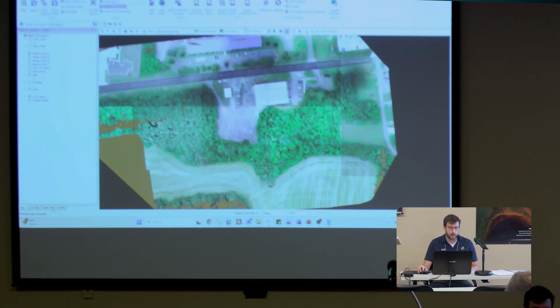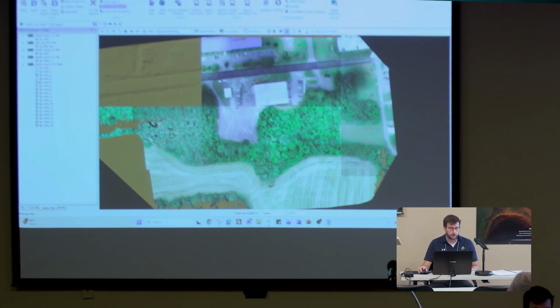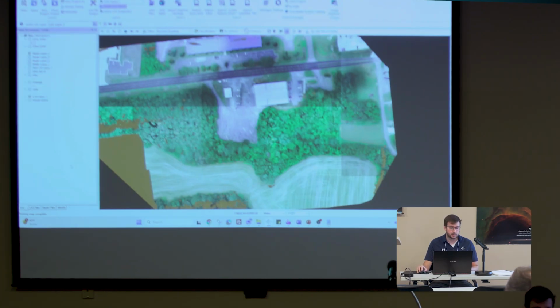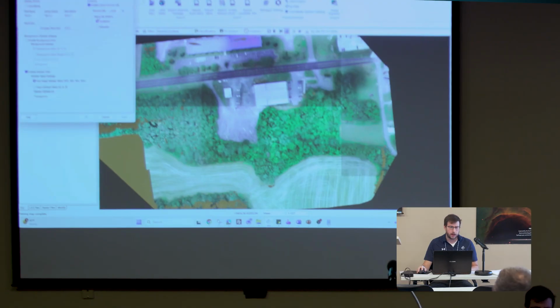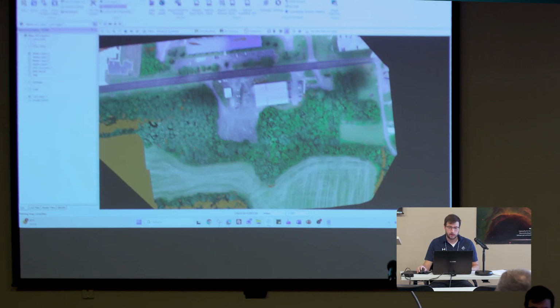If we click on the raster files tab at the bottom left, you can see all of them loaded on a single layer. And we can do things like what we were doing before, turn them on and off here for the display. But I just want to show you, this is a really neat trick. If you get a tiled ortho from someone else, you're seeing this difference in color balance. I'm going to right click on the raster 4 layer where I brought all these in, go to properties at the bottom, and then disable the enable linear % clip option. Disable that and click OK, and see it balances out all the color balance for the tile files.